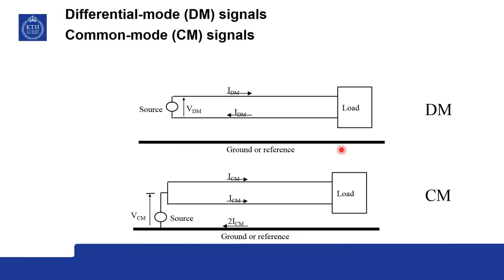So, this is a ground plane. But it could also happen that you have some electromagnetic fields coming from some other direction, and falling on this circuit over here. Then you create a potential difference between your lines and the ground because of the interaction of the electric and magnetic fields, and that will drive some net currents. You can have parasitic elements, parasitic capacitance here or some other connections, and it can drive some currents through these lines, through the ground and back into this.